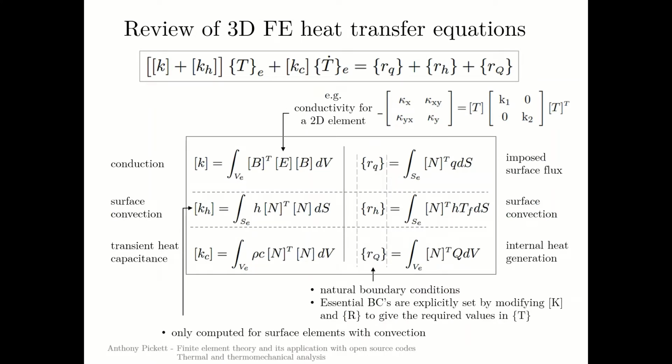This is a summary of the key matrices for heat transfer analysis. These have all been derived in the video on lecture 5, but I just wanted to review the equations here. If you're not so interested in these, you could jump over it, but it's just to give you a chance to look at what the key matrices are. First of all, maybe I'll start here. This is the conduction matrix. So this is computed for all elements in the problem.